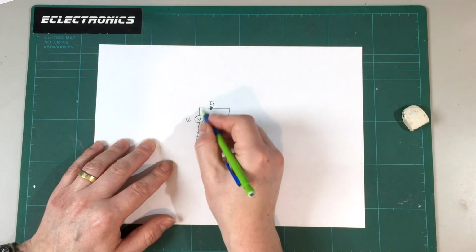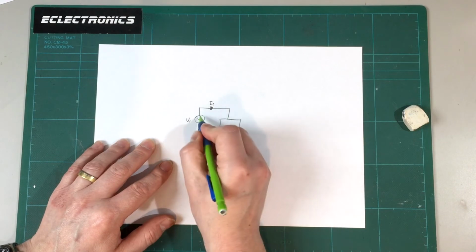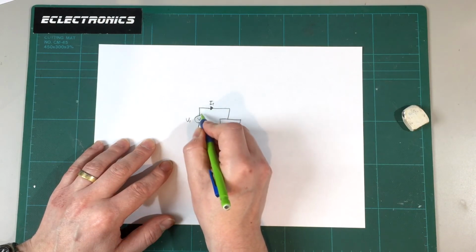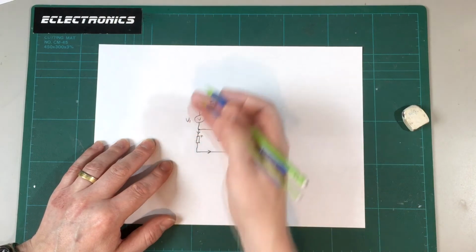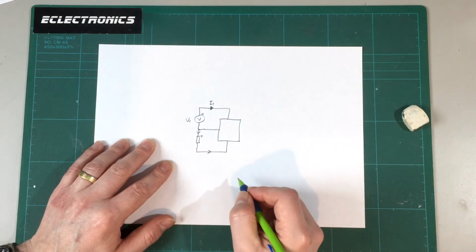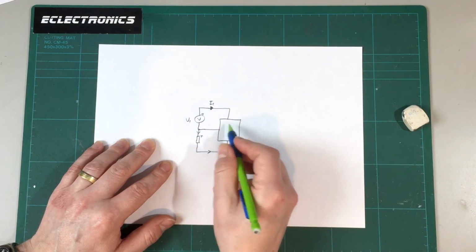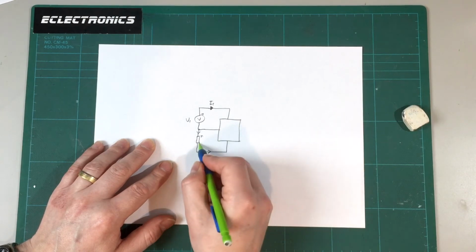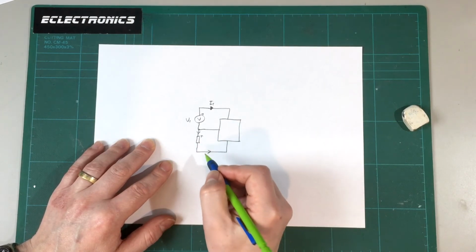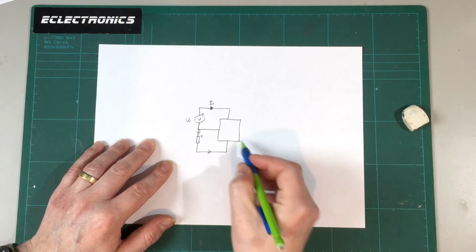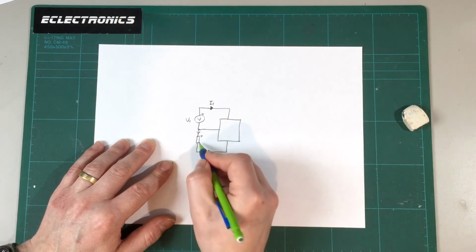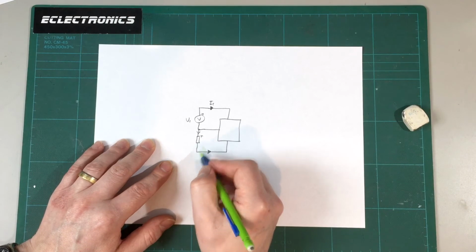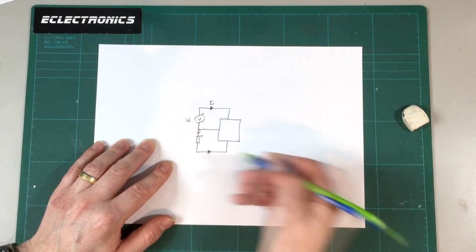So taking charge out of this cell by having current coming out of the positive terminal. On this cell we want the current going into the positive terminal to transfer the charge. So if this circuit powers up in this state, we put a resistive load on there to simulate the lower cell, then we get a current flow in this direction. We get a voltage drop on this resistor, and we could measure some kind of characteristic curve that way.